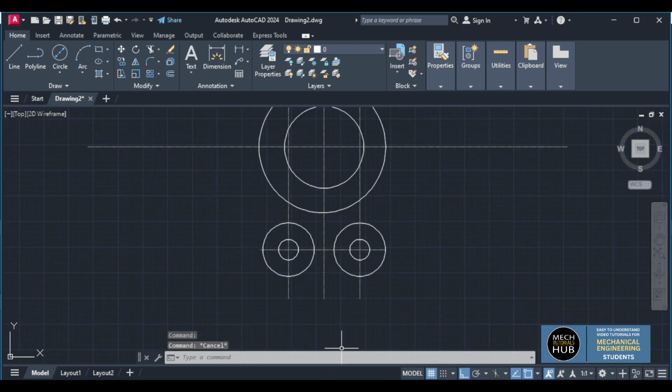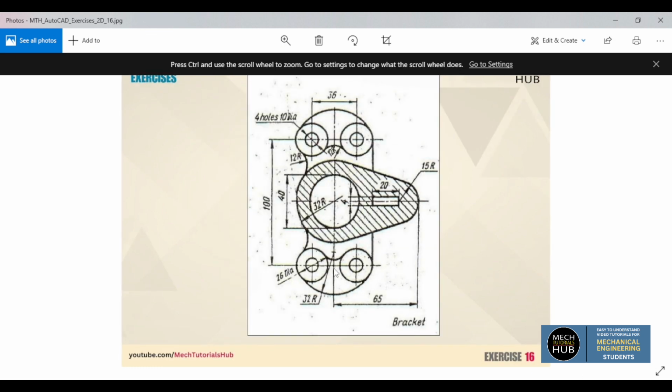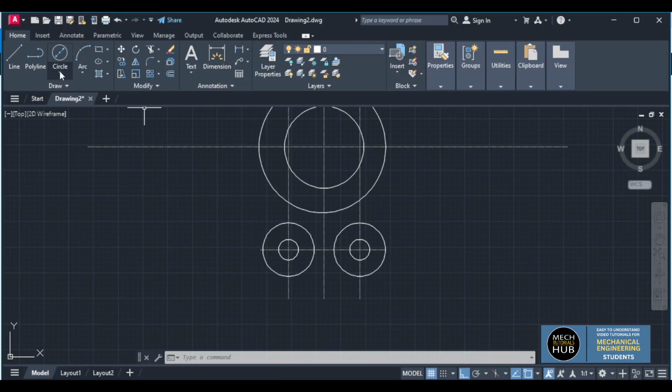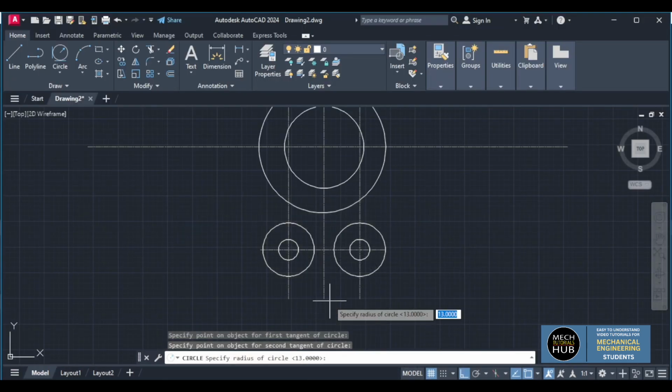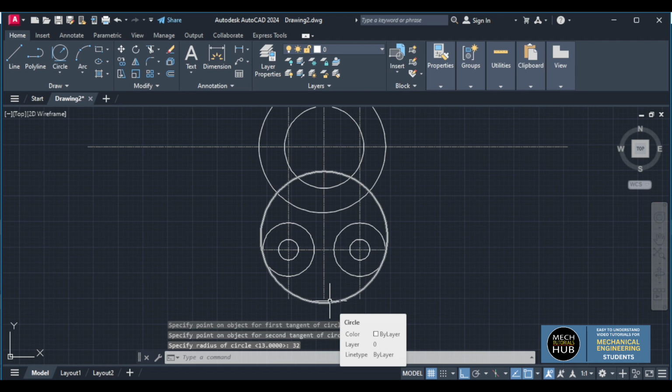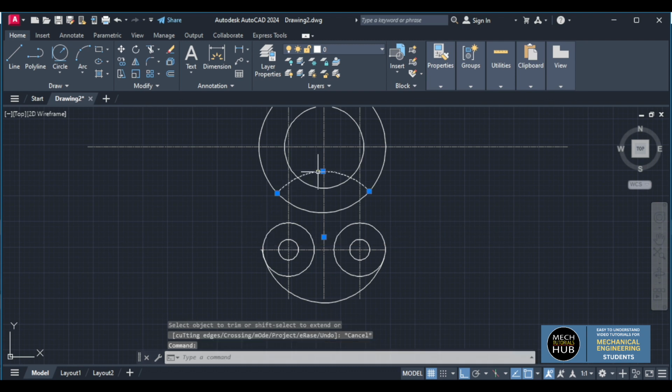This is completed. Now the bottom half there is one more curve of 32 radius, but where exactly the center of the curve is, that we don't know. So what I'll do, I'll have an option called tan radius here, tangent and radius. I'll take that from here to this point. There should be a radius of 32. Yeah, correct. TR double enter. Unwanted things I'll remove. This is not required. This is also. So internally the complete curve I'll select and delete.